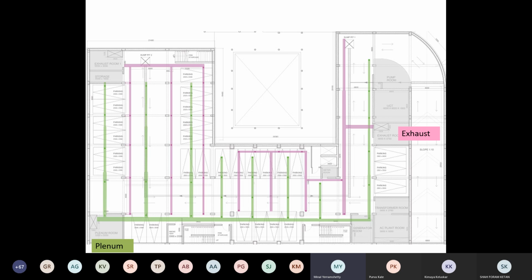So ideally at the end of the duct there will be a jali, which can be cleaned, taken out, cleaned, and then fitted in again, and then you will allow the carbon monoxide to be taken up. And this has to be done between every 2 to 3 cars, depending on where the column is available. But even if you give between 3 cars at least one spout that is coming down, it's good enough. Are we clear what I'm trying to say?